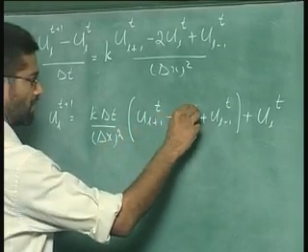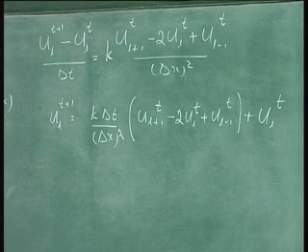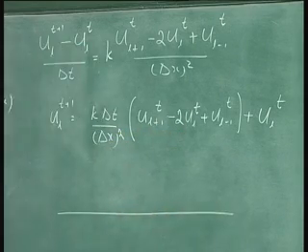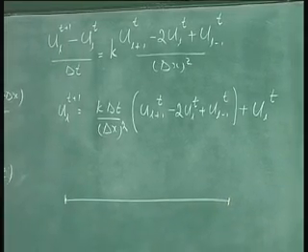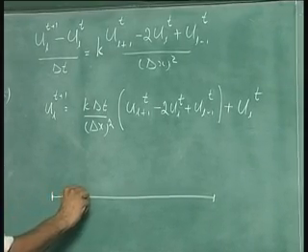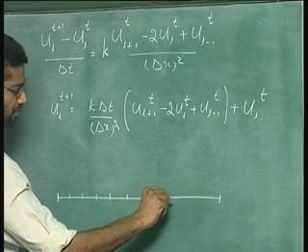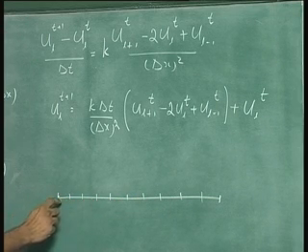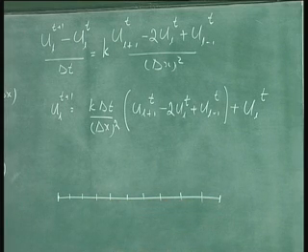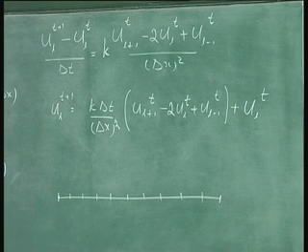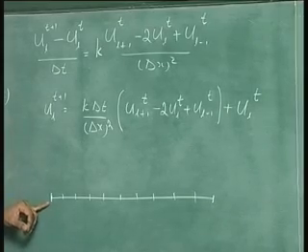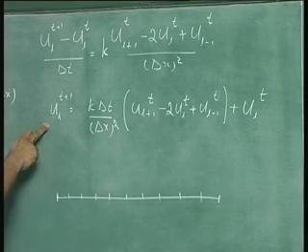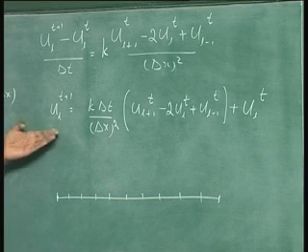So this is easy to solve because at a given time, for example t equal to 0, or at any starting time, we have been given the temperature at all the points. We have this particular long thin rod, and we have been given the conditions at the boundary. We discretize this into equal intervals in space, with interval delta x. At time t equal to 0 we know the temperature at all the points. Then at time t plus 1, that is t plus delta t, the temperature is given by this equation. The right hand side is completely in terms of temperature at t, and the left hand side gives us the temperature at t plus 1. So using this equation we can easily solve this.